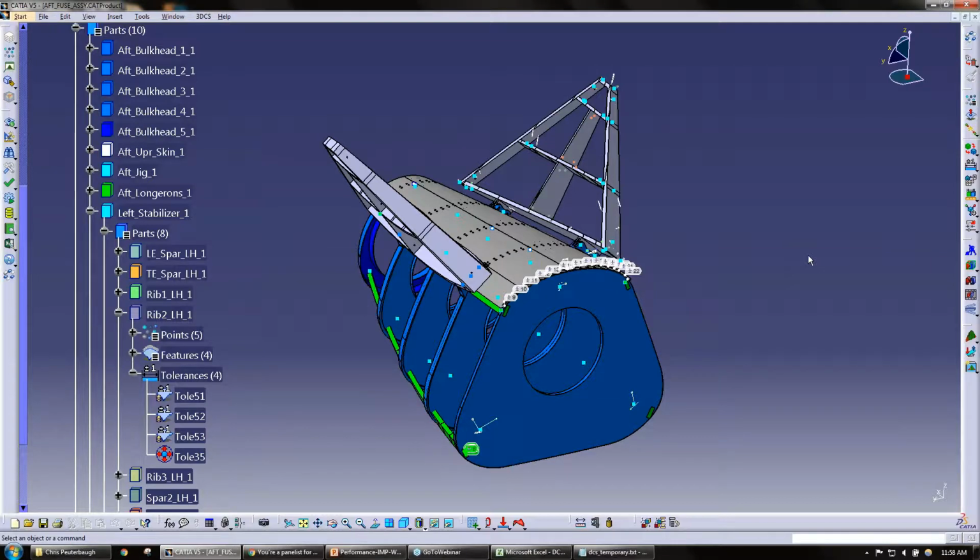So that allows you also to have multiple databases available. So if you've got, as Chris mentioned, different variations on your specific design intent, or if you've got different suppliers that hold to different tolerances, you can create different databases, each representing a different set of tolerances. And then by uploading different databases, you can quickly change all of your tolerances to new scenarios.